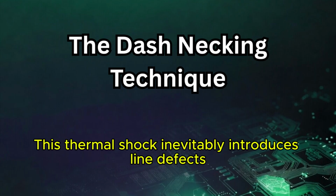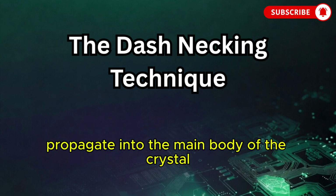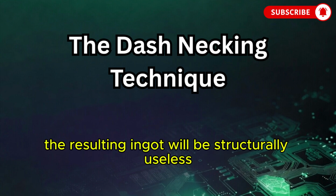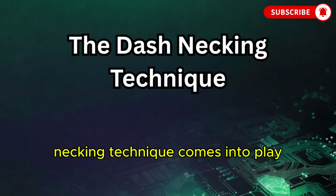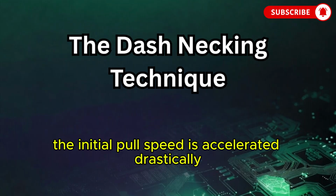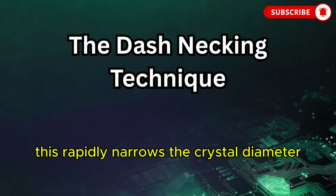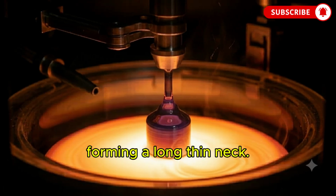This thermal shock inevitably introduces line defects known as slip dislocations. If these dislocations propagate into the main body of the crystal, the resulting ingot will be structurally useless. This is where William Dash's necking technique comes into play. To eliminate these defects, the initial pull speed is accelerated drastically. This rapidly narrows the crystal diameter down to a mere few millimeters, forming a long, thin neck.